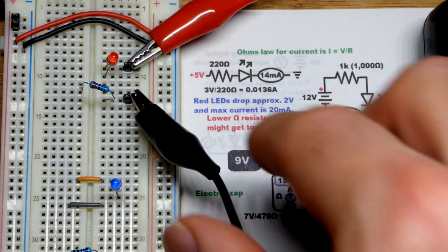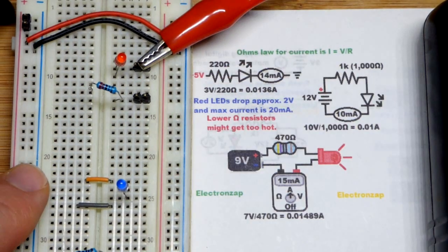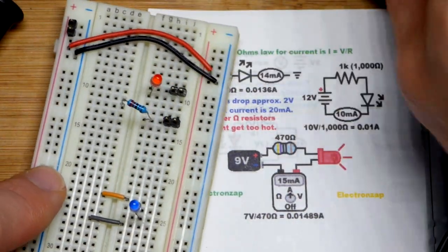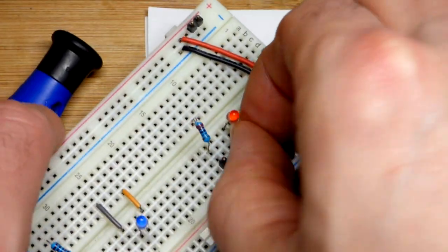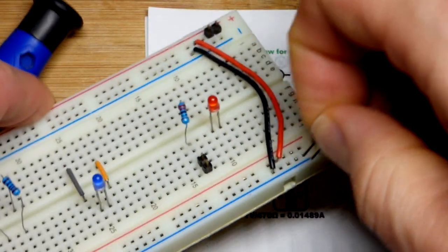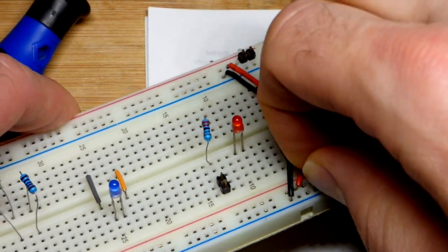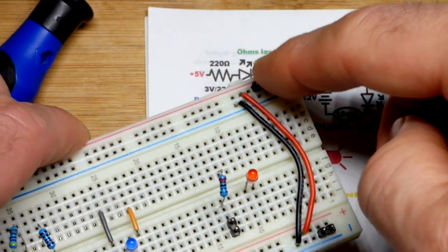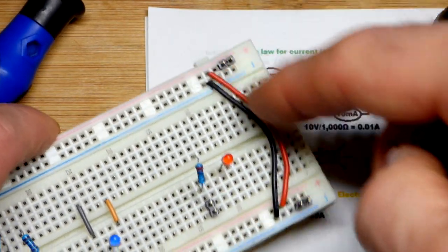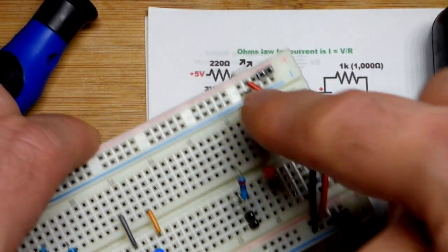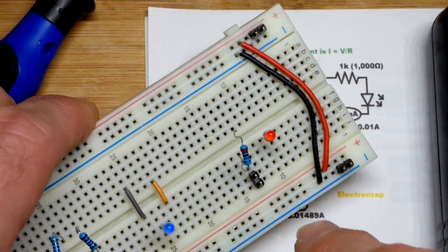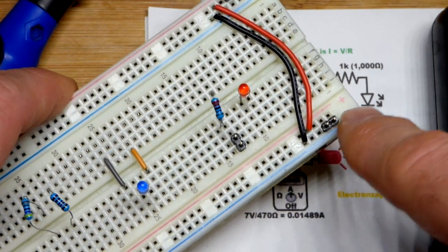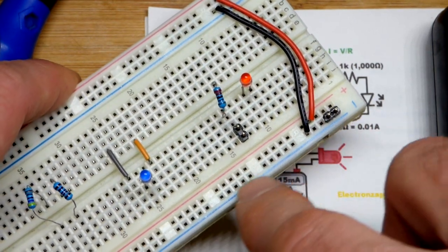So now we're going to rewire the circuit right here. I'm going to unplug these, and in fact from now on I'm not going to connect across here. So I'm going to pop this back out and put it back to the negative supply right there. So I can plug the positive alligator clip there, and it would also power this side over there, both of these rows next to the red line, and then plug the black alligator clip from the power supply there.